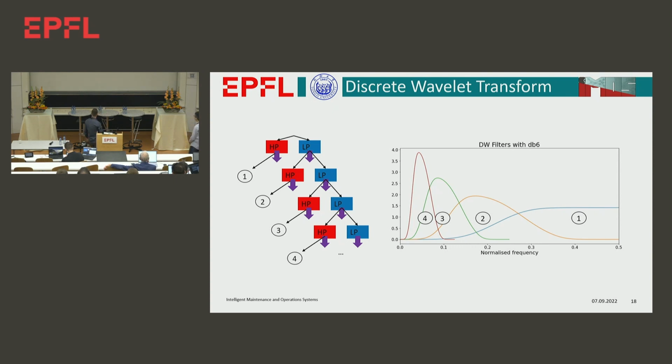What is interesting here is that we will then have different outputs with different time-frequency resolution. The first output will have a bad frequency resolution on the high frequencies, but a very good time resolution. And over the low frequencies, we will have a better frequency resolution. It will imitate a bit what we use a lot for time signals, like, for example, a mel spectrogram, where we focus more on the low frequencies.